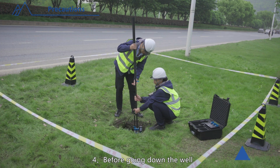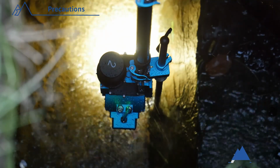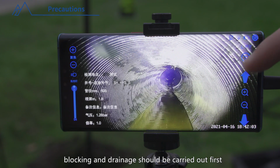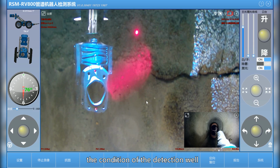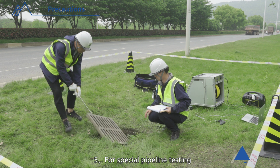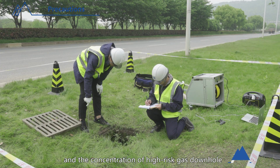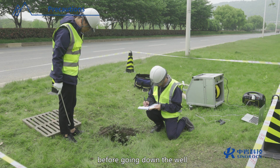4. Before going down the well, use the pipeline periscope to check the inspection environment in the pipeline. If there is silt or a large amount of flowing water in the pipeline, pre-treatment measures such as dredging, blocking, and drainage should be carried out first. If necessary, the condition of the detection well can be recorded with a periscope as required. 5. For special pipeline testing, it is necessary to check whether the environment in the well meets the safety requirements. And the concentration of high-risk gas downhole should be tested in advance before going down the well.